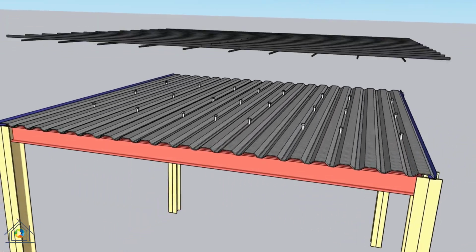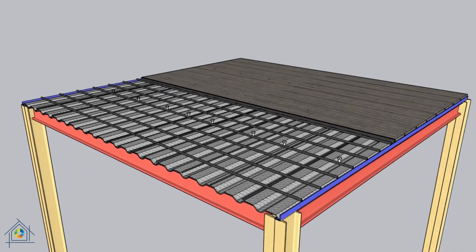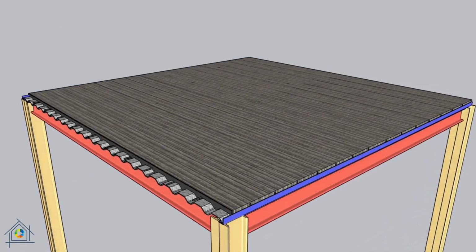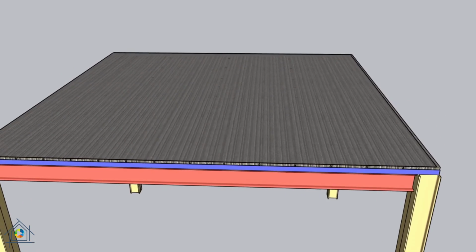Concrete in slabs is prone to cracking due to shrinkage and thermal expansion. For this reason, first the shrinkage and temperature reinforcement is applied in a grid pattern and then the concrete is applied with a minimum cement content of 250 kg per cubic meter. The thickness of the concrete and the details of the reinforcement are determined based on structural calculations. A layer of nylon is applied as a vapor barrier on the concrete surface.